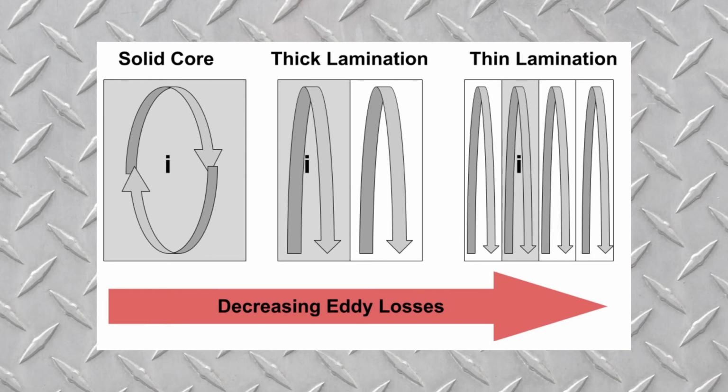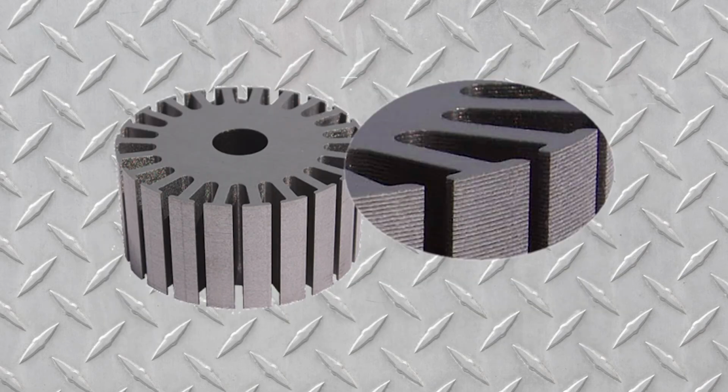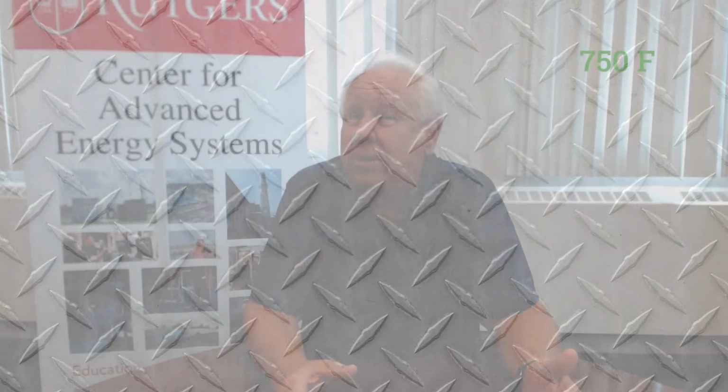So when we're redoing the windings, we have to get the old windings off, and that's called stripping. And we have to strip the old windings off, and generally we use heat to do that. Well, if we use excessive temperature, we can create problems with those laminations in the core, and thus we end up having more eddy current problems in the core. So the typical rule of thumb in the rewind process is you should never go above 750 degrees Fahrenheit. But guess what? To speed up the process, a lot of these burn-off ovens operate up to 1400 degrees Fahrenheit. And that causes the insulation between the laminates to be compromised, which then reduces the efficiency of the motors.